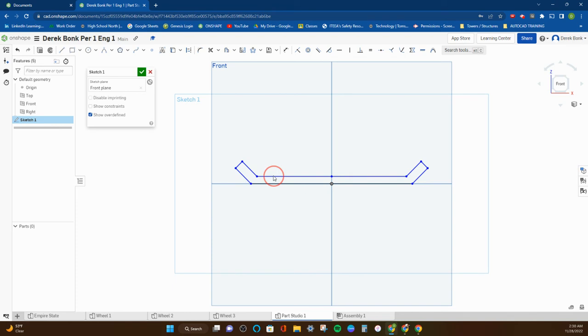So if I want to update my design a little bit, make the ends a little bit longer, or even get super technical and dimension this out where I create a specific angle here, since that's not quite right, I can push those out and get the right angles I'm looking for. If I wanted to make this longer, again I would have to escape out of the tool so I get a white arrow, and I can pull this out a little bit further.